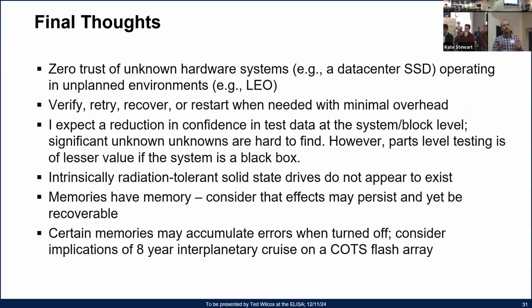There's a temptation to take the drive, put it in a radiation beam and do a single event latch up test only, put high temperature on it, potentially elevated voltage if you can, and you're really just screening out destructive effects. And that is how CMOS devices can be loosely approved for high-risk missions. You're at least screening out all of the bad stuff that will kill the device.